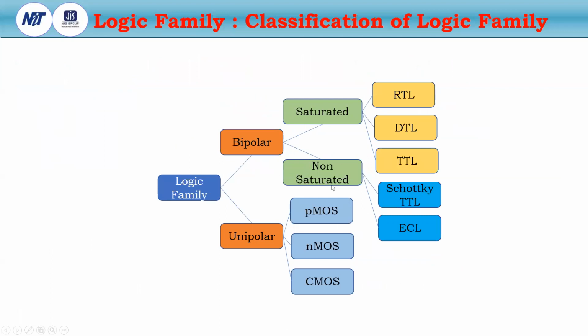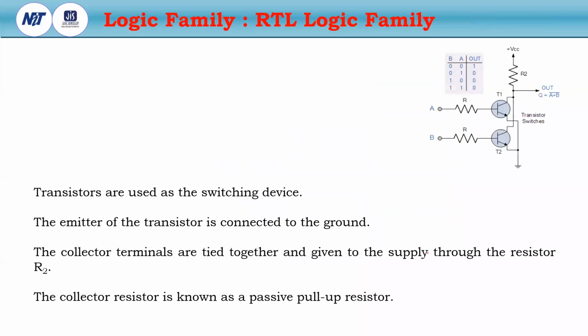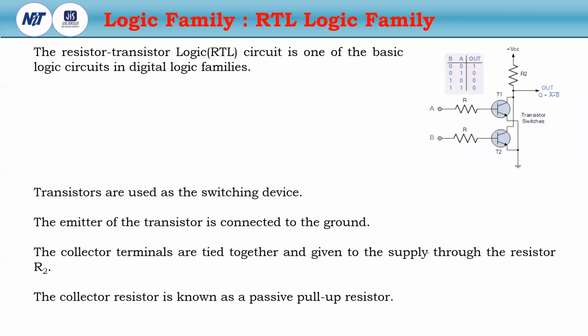So this is the classification which we already know. We will cover RTL, DTL, and TTL, the saturated type of logic families, these three, and the non-saturated, these two, Schottky TTL and ECL, in today's lecture. So first, I want to cover the RTL logic family.